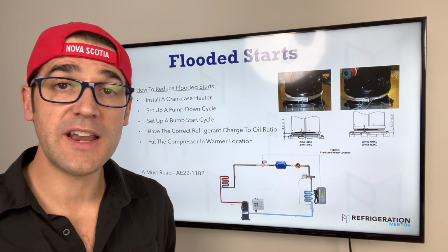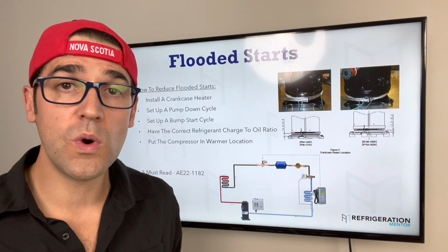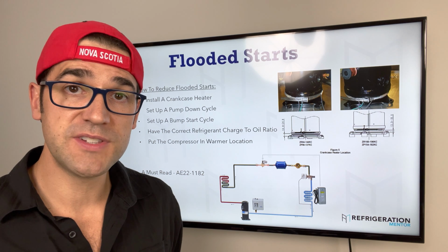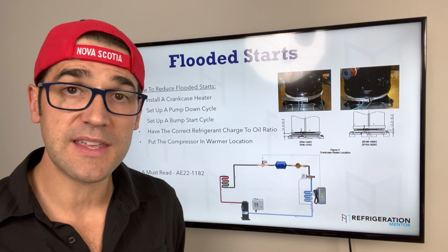Okay, another thing: set up a bump start. So what is a bump start, Trevor? Well, that is where you start the compressor up for 2 seconds and shut it down for 5, 6, or 10 seconds.